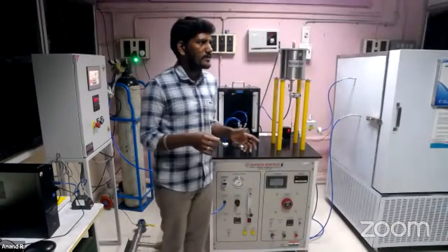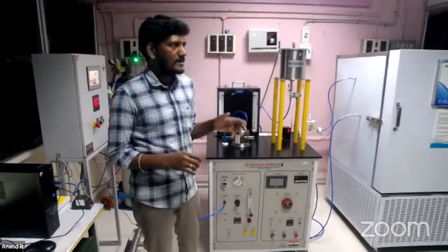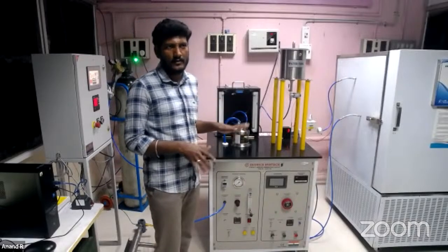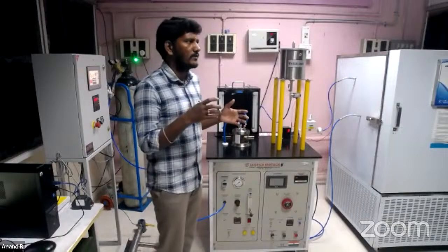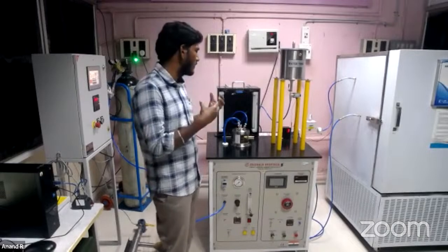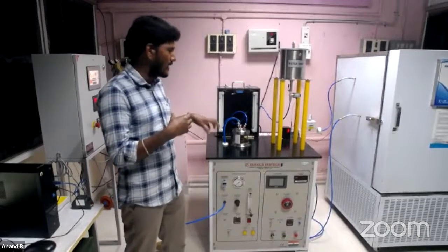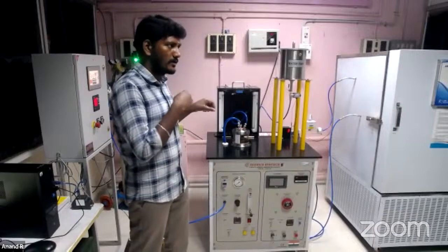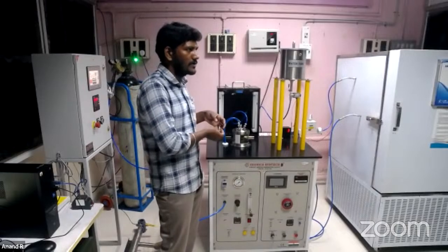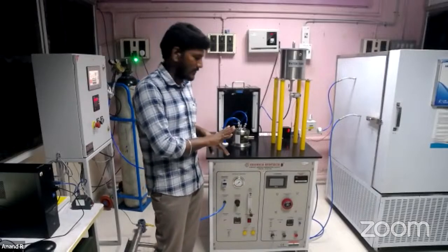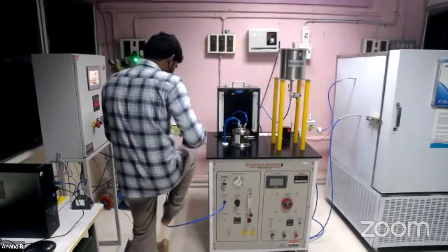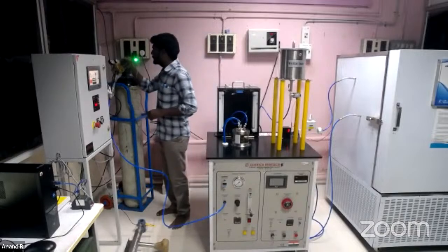So in this session, we are going to discuss the nitrogen flow regulation. With respect to the nitrogen flow, how the ammonia generation and the plasma will vary. Here, the plasma medium is nitrogen. We are giving nitrogen gas so that it will become a plasma, and it will dissociate. It will also dissociate the water particles, and they will combine with the hydrogens to form ammonia. So here I am going to start the demo by supplying the nitrogen for ammonia generation.